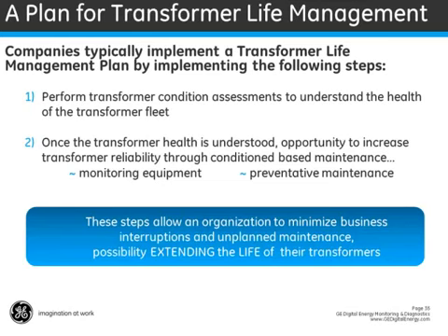The benefit of an online monitoring system is not to prevent a fault from occurring, but to prevent it from developing into a major failure and to be able to warn the operator before this is potentially going to happen. For that reason, the gain from reduction in major faults will be somewhat attenuated by an increase in minor faults or predictive maintenance actions. With a good plan in place, life extension of existing transformers is possible and will help companies address a specific unit or population of issues.